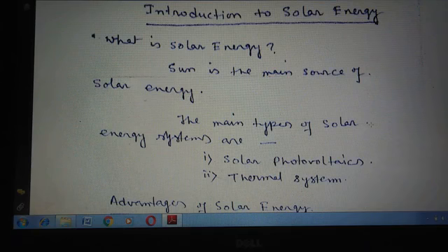and the solar arrays are placed on the ground, by which DC voltage is developed. The DC voltage is connected with the solar charge controller or pump controller, which converts the variable DC into a stable DC. Now the inverter converts the DC into AC, and this AC is connected with the pumping system. So these are the main principles of the solar pumping system.